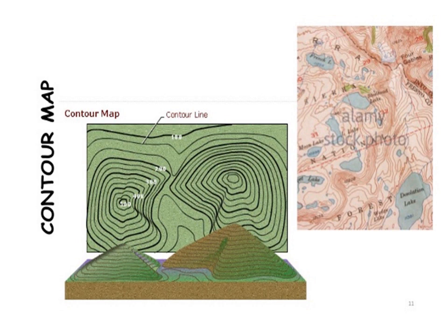They are 100, 200, 300, 400, 500 and 600. Whenever the value of contour increases, it indicates the increase in the level with respect to the datum. Therefore, in the given contour map, a hill feature is shown.